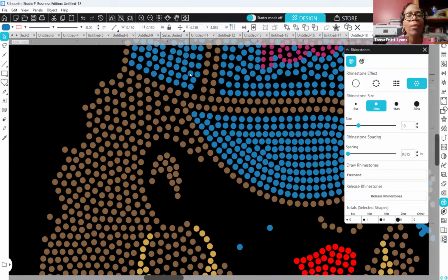We probably could, right? We could shift this up and shift that up out of the way for the moment. Shift that like that. Go ahead and add a stone in that corner, right? Add a stone there. And again, I'm using my Alt key and I'm dragging that stone out after I do that. So once we do that, we could then come back in here, and then we just do our equal spacing. We select that, hold our shift, come in here, make sure we select all of those stones.